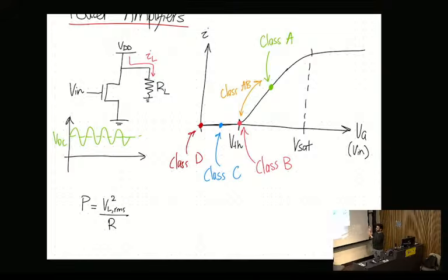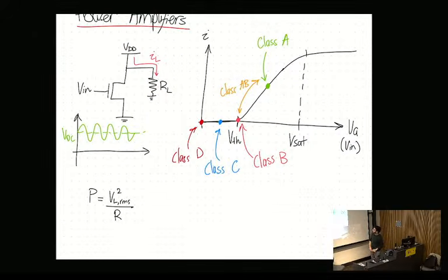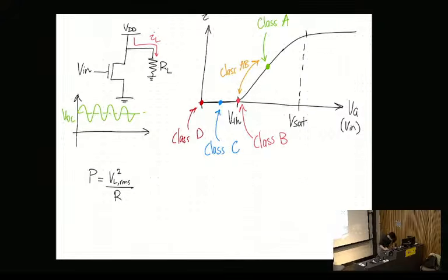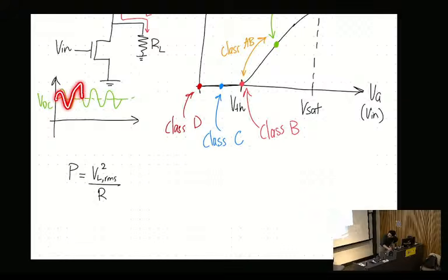So this is fundamentally, when you're building your own power amplifier, really the first thing you need to consider: what class of amplifier do I want to be in? And now there's a small caveat with this, that the amplifier I drew on the top left doesn't actually work for class B. Does anyone know why? The method of operation is roughly like the explanation I gave here and applies to all amplifiers, but class B swings low. If you look at class A, for instance, it's always positive. It never goes below to the negative axis. Class B, however, goes negative.